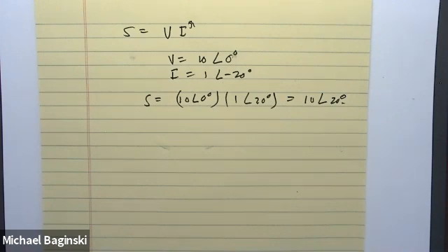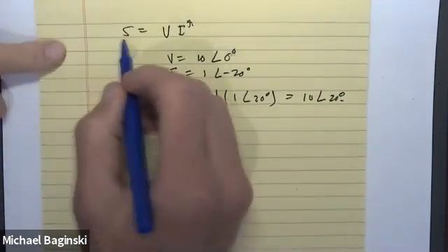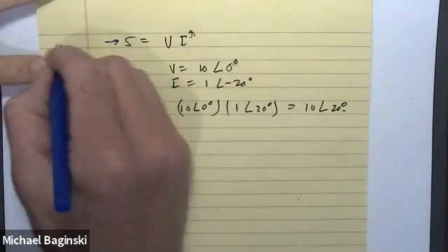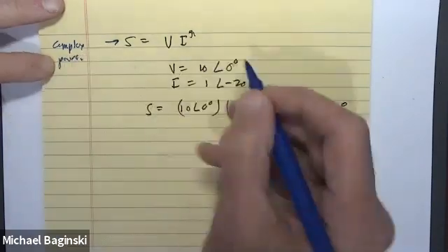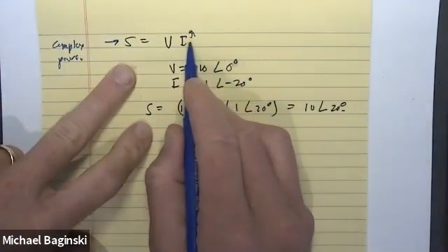Now, on the PowerPoint that I provided, there is information about complex power. But from at least a couple of comments I got prior, the PowerPoints don't seem to be absolutely clear. So this is the reason I want to take time today to talk about how to calculate it and then why it's so important, okay? All right, so in general, when we talk about complex power, the symbol is S. S is V times I conjugate.